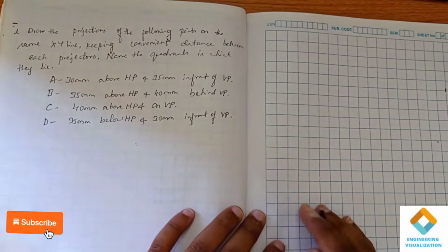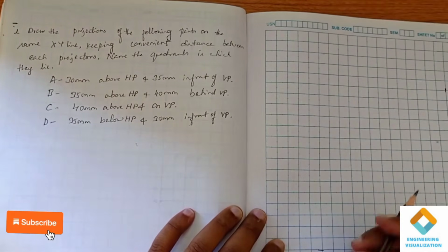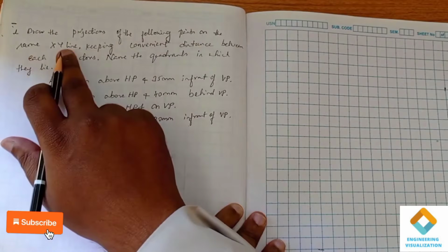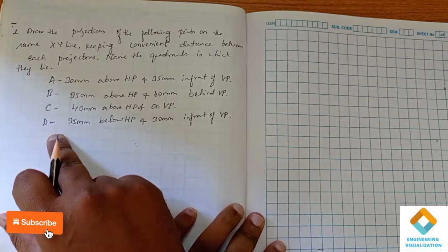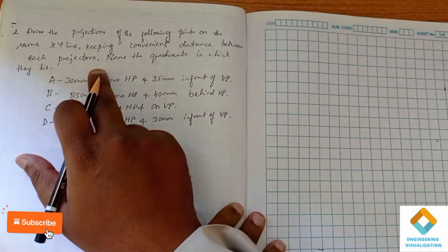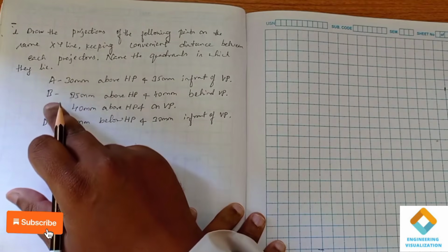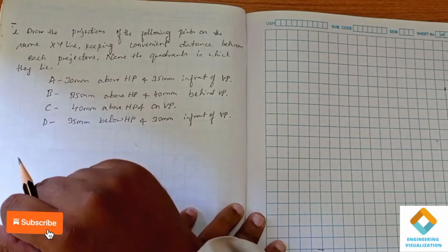Okay, so this is the problem. In the basic problems which you have solved, there was only one point on the XY line, but in this problem we need to project all four points A, B, C, D on the same XY line, keeping convenient distance between each projector. After that we have to name the quadrants in which they are lying. We need to mention whether A is lying in the first quadrant, B in which quadrant, C in which quadrant, and D in which quadrant. So that we have to do.